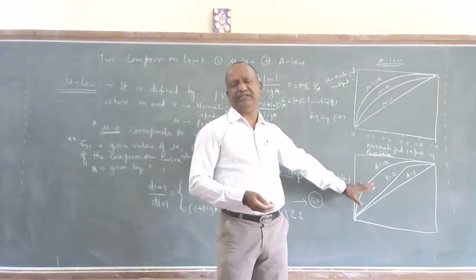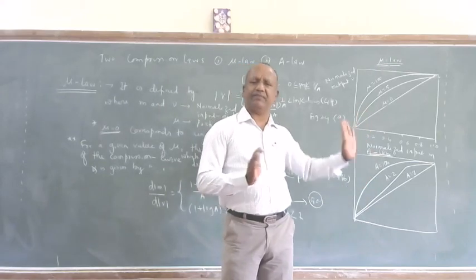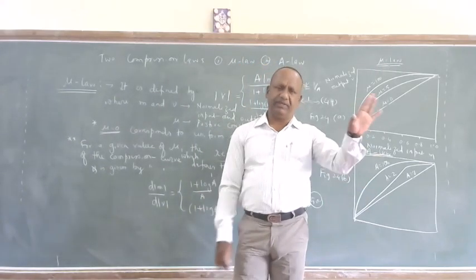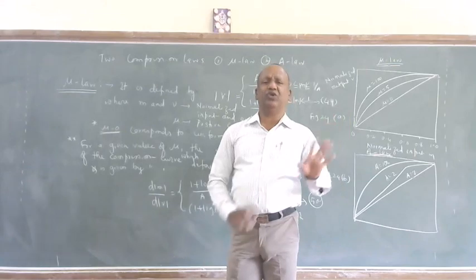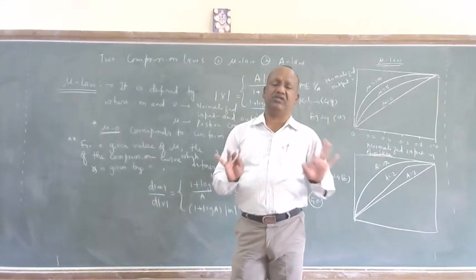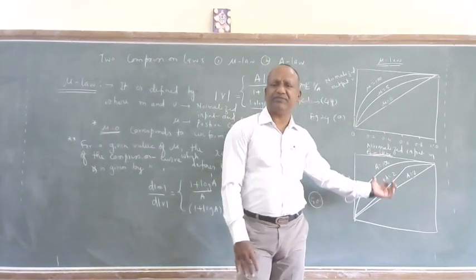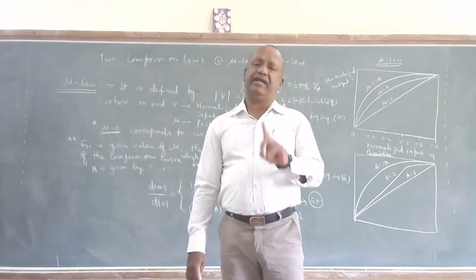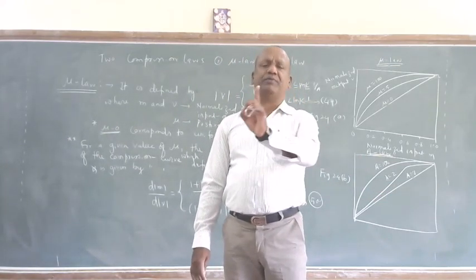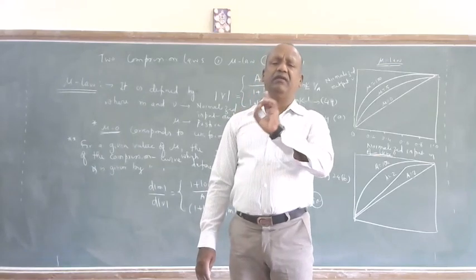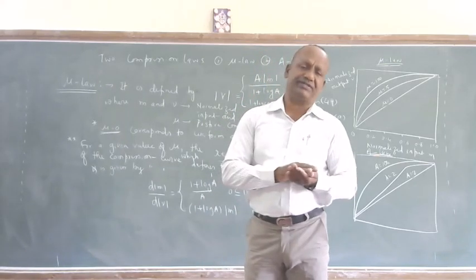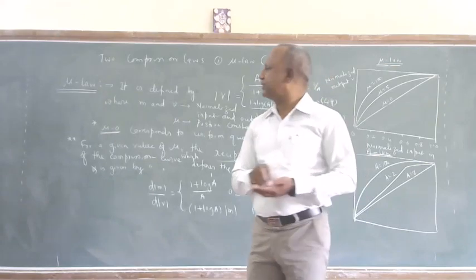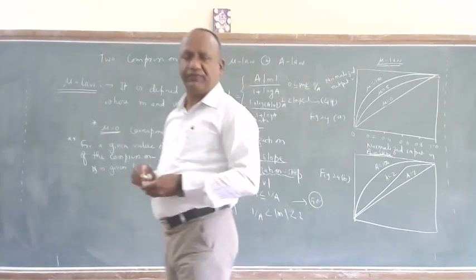Whether we adopt this or this, it is a part of A to D conversion in the PSTN network, so that it becomes compatible internationally. Why do we use these standards? Because the standard is defined worldwide, and if you adopt it, it will be processed by any industrial product, equipment and components. So with this, the quantization process related to non-uniform is complete.